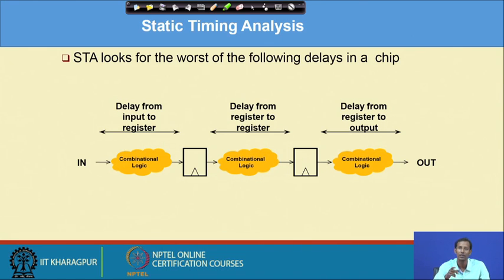So, that is why this gets the highest priority, the clock one. That is why this is a clock-dependent, not data-dependent, sequential element. Okay, got it. And for that particular property, if we put the registers in between, then C1, C2, C3 become individual to each other.